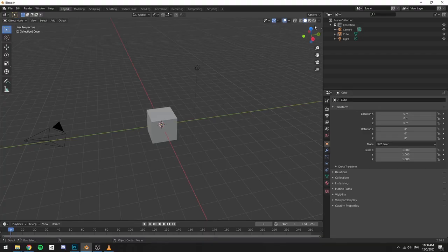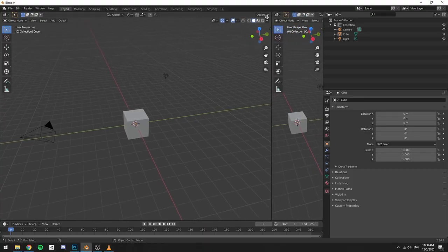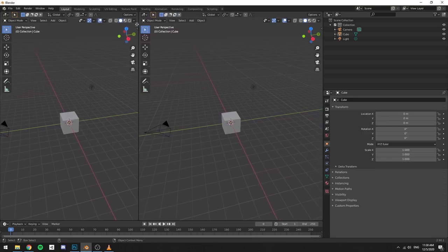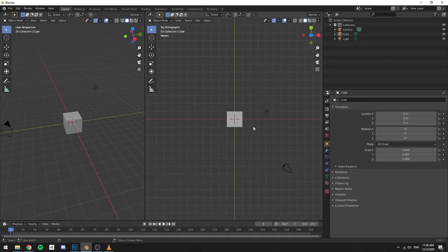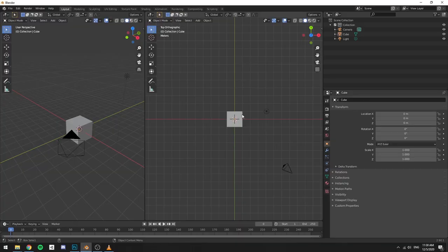So you need to go to the edge of each window over here, and as you can see, my mouse will turn into a crosshair, and you just left click and drag to the left, and I'm just creating another window. All right, so we have now 2 viewports, and if I want this viewport to see my model from the top, so for example, if I'm modeling something over here and I want to see how it looks from the top, you can pretty easily create that.